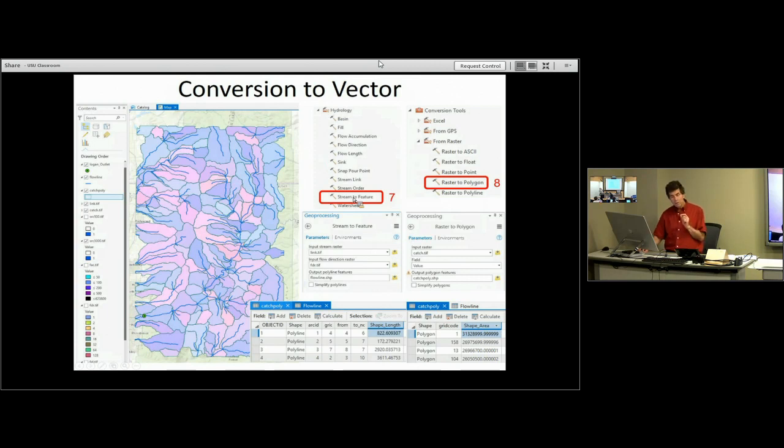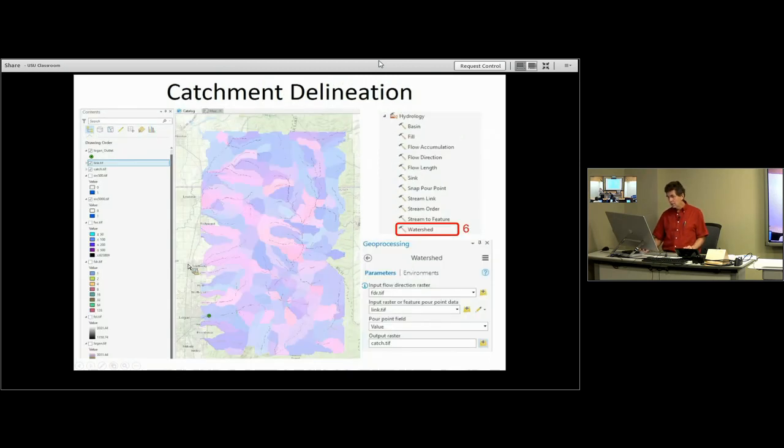And when you're looking at this visually, you can tell that we've got vector information because it appears as crisp lines on the display no matter which resolution I'm using, whereas if I went back to the raster representation, here these lines look a little bit discontinuous. That's because I'm zoomed out so far that the resolution of the data is finer than the resolution of the pixels on my display, and sometimes it leaves gaps. If I was to zoom in, the gaps would get filled in.